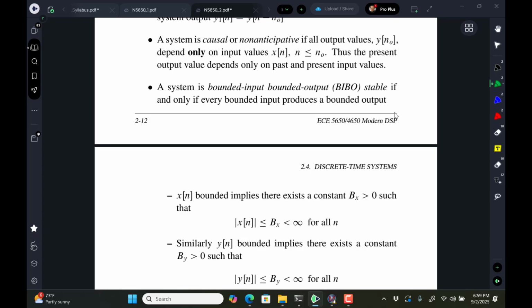So there's nothing you can put into a system that's bounded that will cause it to go unbounded if it's stable. On the other hand, if it's unstable, then you can hit a resonant point in a system, and it will blow up. The classical mechanical engineering example is the Tacoma Narrows Bridge, which I remember seeing probably in physics. The wind shear came along, the bridge started oscillating, and something in the wind currents was resonant with the bridge and the canyon that it's in, and it grew and self-destructed. We can build systems like that in DSP, as rarely as you can in analog.